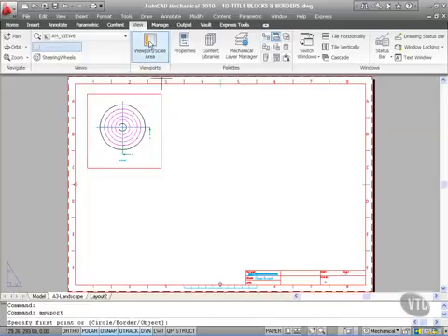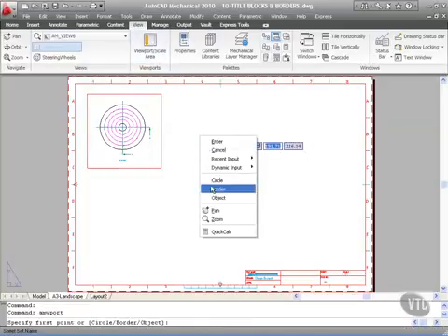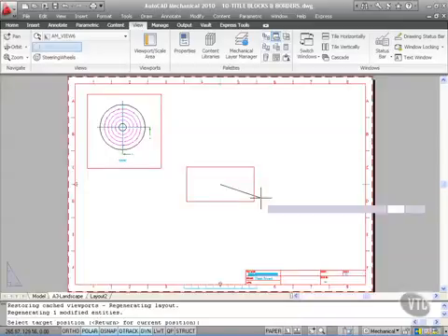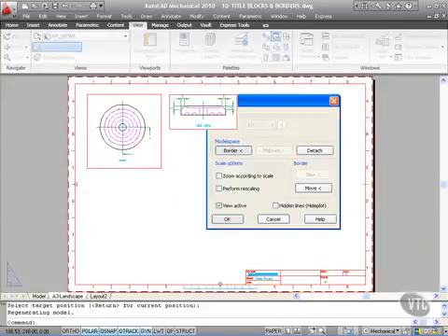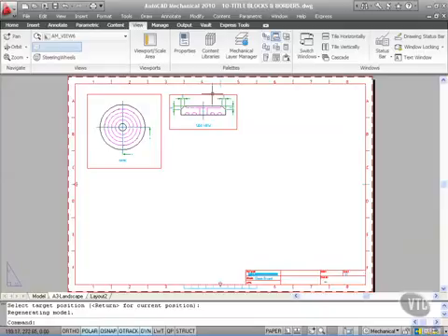So if I do another viewport scale area, right click, border, straight back in, I'll select this scale area here. I'll drop that one there. Just OK that now, and there you go. There's my side view, straight in, with a viewport at 1:1. Easy when you know how. So utilise your title blocks and your borders to make yourself quicker, more productive and more effective.